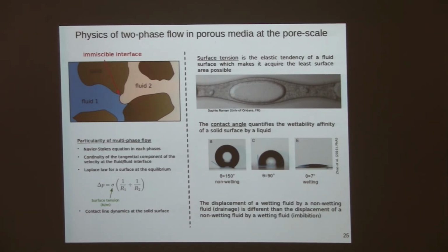You don't have continuity of stresses because of Laplace law. Laplace law says that you have a pressure jump because of the curvature of your interface. Okay? So you don't have a continuity of pressure. You really have a pressure jump because of the curvature of your interface. And if you want to simulate this problem, you will need to compute the curvature of your interface at every time step when you apply the boundary condition at the interface between the two fluids.